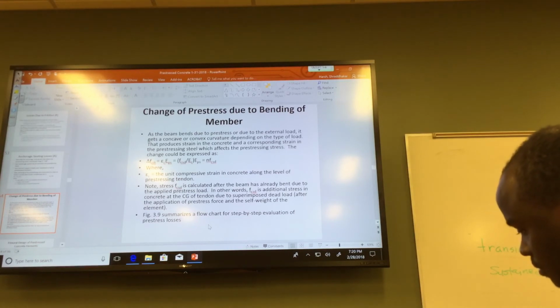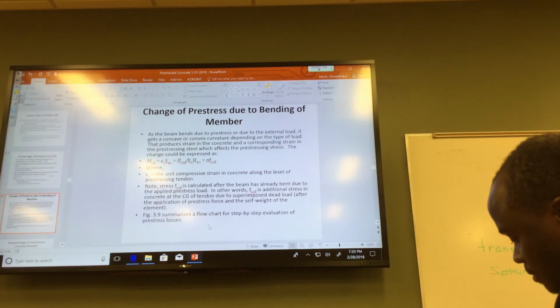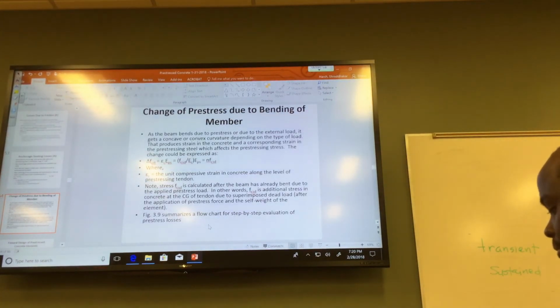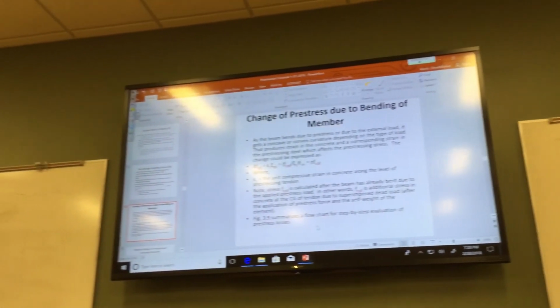So I think when you talk to geotechnical engineers, for example, they don't use live and dead load. They use transient load and sustained load. That's what they say, and I agree with that because for geotechnical engineers, it's the same phenomena, especially if you're dealing with clay type of soil, because clay responds time dependently. And sandy and silty soil do not depend on time. Your response is right away. As soon as you apply the load, there it is, right?